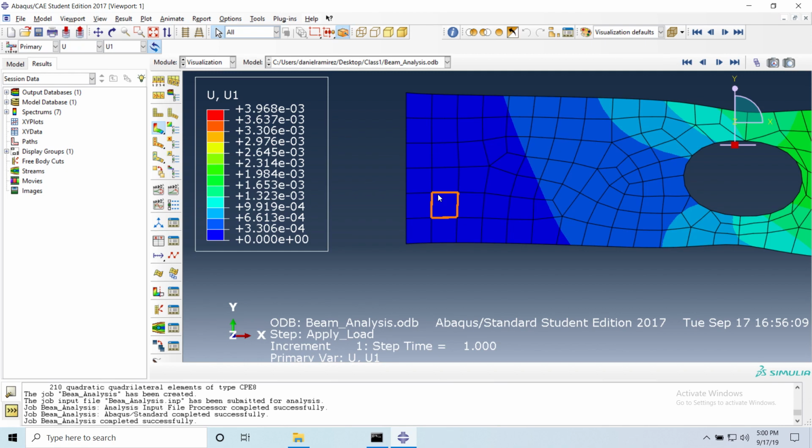But it's some specific energy quantities and scalars, or if you have damage. So for example, hey, I want for this particular element damage history. That's why it's called the history output request. So from time step 0 all the way until the end of your simulation, show me how the damage in that element evolves. Okay. Would that be something you access through the drop-down menu, or is that something you can